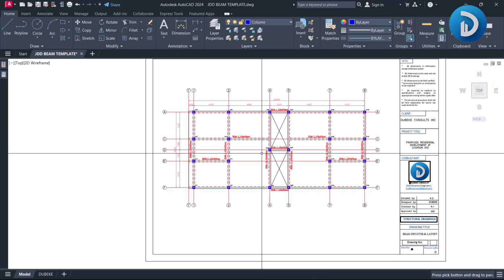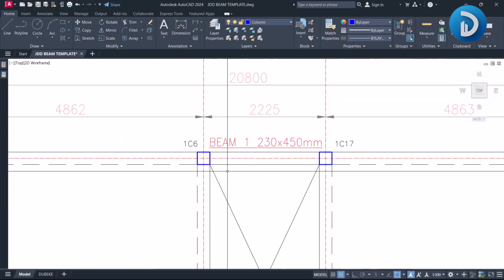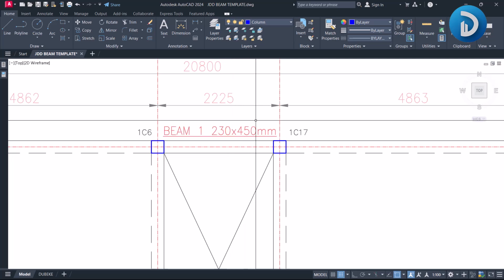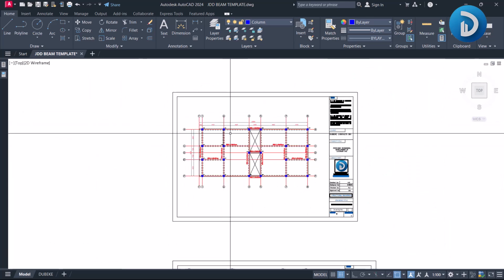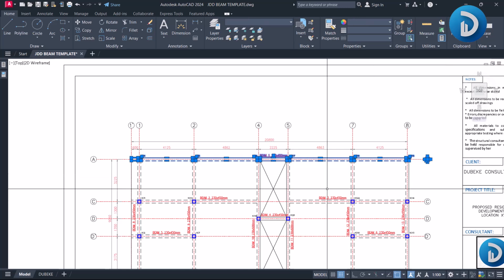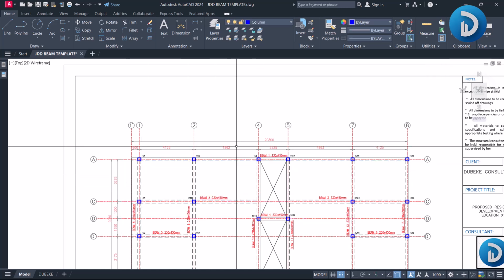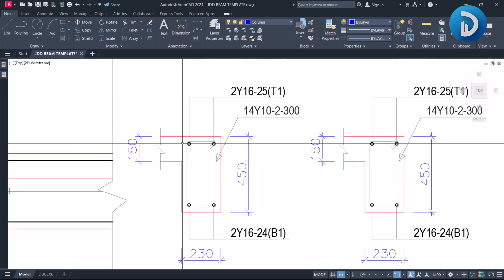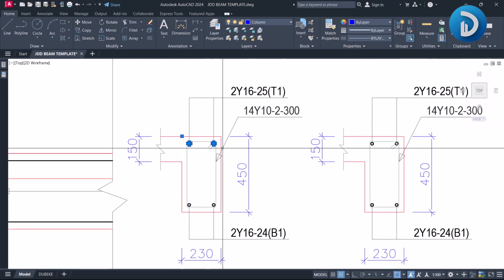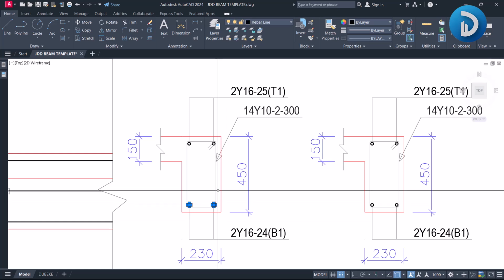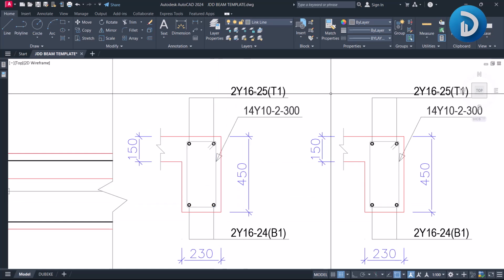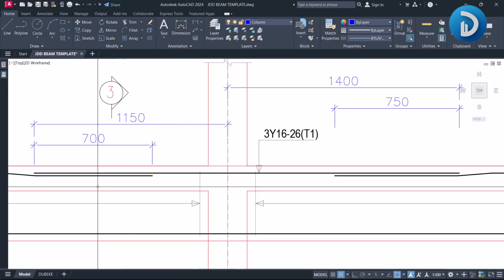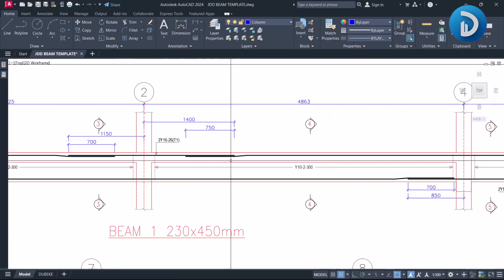While your beam structural layout should comprise vital information like your beam name, the width and the thickness of the beam, and also show you the grids on which they run, your beam sections should be able to display further information like the reinforcement at the top, the bottom reinforcement, and also your links. It should also show further information like your curtailment length and your cranks where necessary.